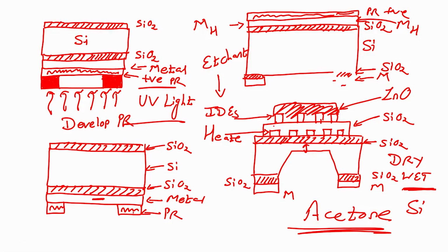So, it is a lot of process. So, if I do not do this backside etching, then it is easy. If I do not do this backside etching, then my sensor becomes extremely easy, because I had to just keep on growing the heater, then I had to grow the oxide, on that interdigitated electrodes, on that I had to grow the sensing layer, that is it. But the power consumption is high, that is why I have to etch the wafer from backside.